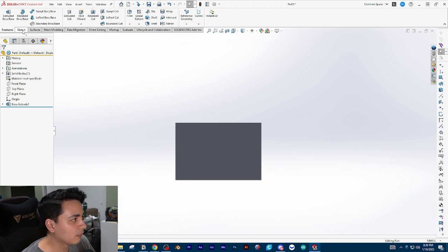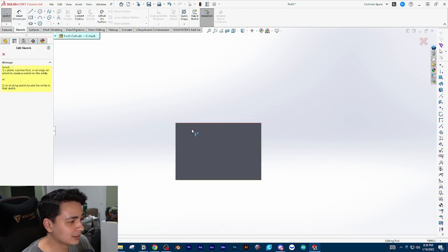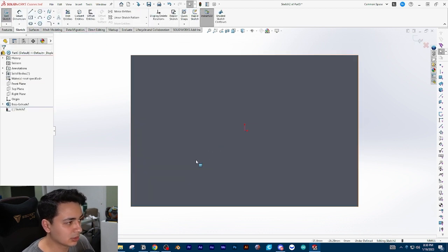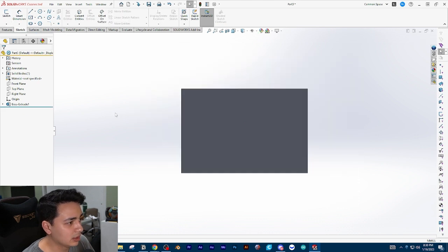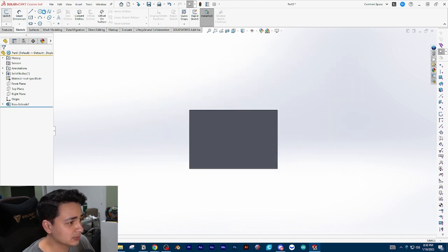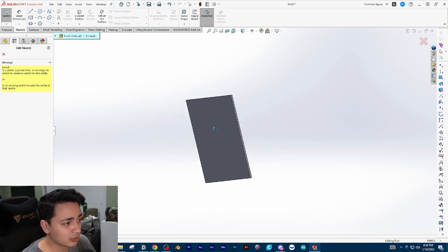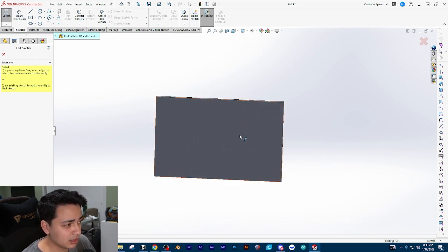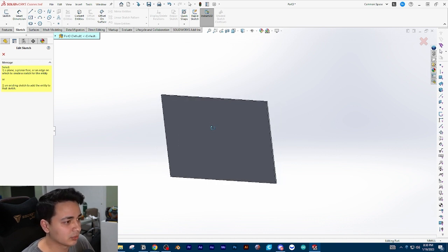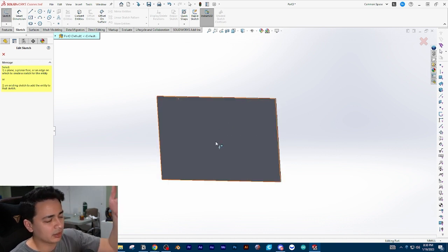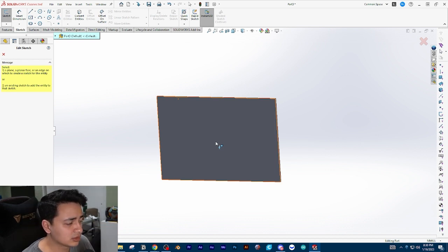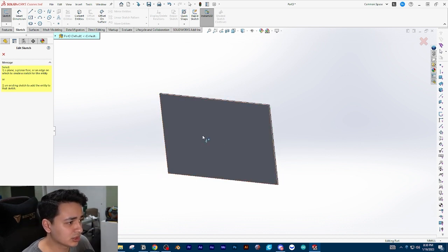So now we need to add the actual entrance to our cave. So what are we going to do? We're going to create a new sketch, and it's going to ask for a plane. And now that we have parts, we can pick things on our part to base the rest of our model on. So we basically want to cut out a portion of the front window. So let's do that. So now we're going to snap to this window.